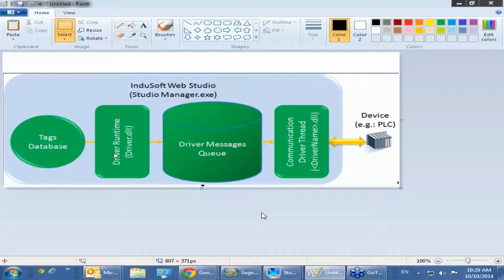Actually, when you have a network, our ZigBee would be part of our network. It means the whole network is a Modbus network, and you have a master, and you have some slaves. What ZigBee will do is just provide us some wireless communication. And this is the general setting and configuration which you do for slaves and master in a Modbus network. But here you need to consider that you have ZigBee as part of your network, and it has one host and then some slaves, maybe one slave in your ZigBee network as well.